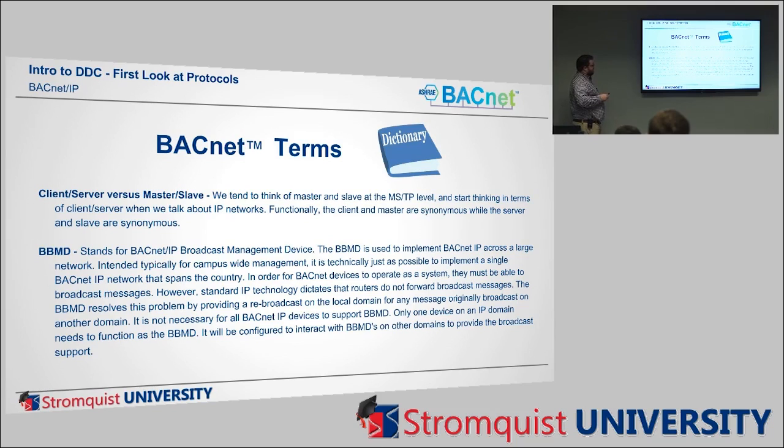And a BBMD is a device that can be embedded in a router or can be a separate device, and that handles if you go across the internet and you have a router on one network and a router on another network, that's how those 2 routers talk.